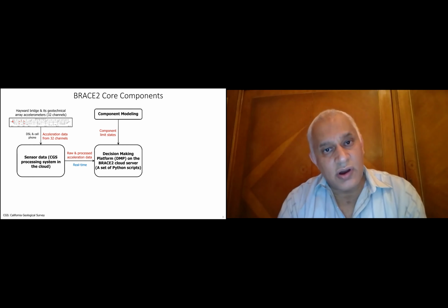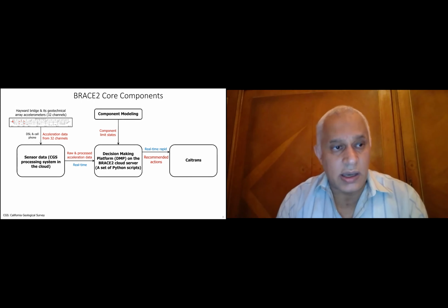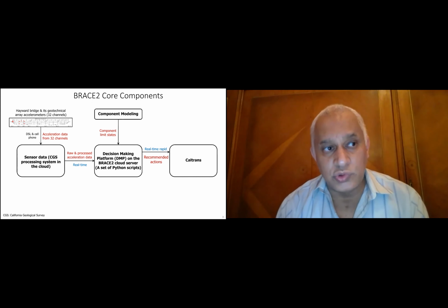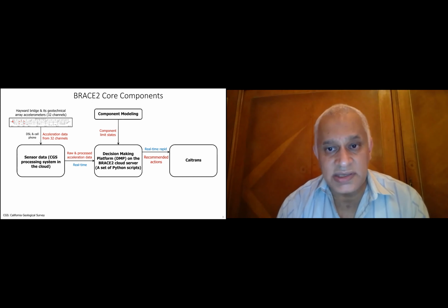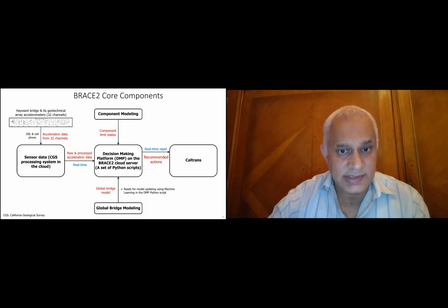The bridges are modeled through their components, so we can determine the limit states of the different components. And by comparing the computed demand to the limit states, we can make a real-time rapid assessment and provide the recommendation for that.